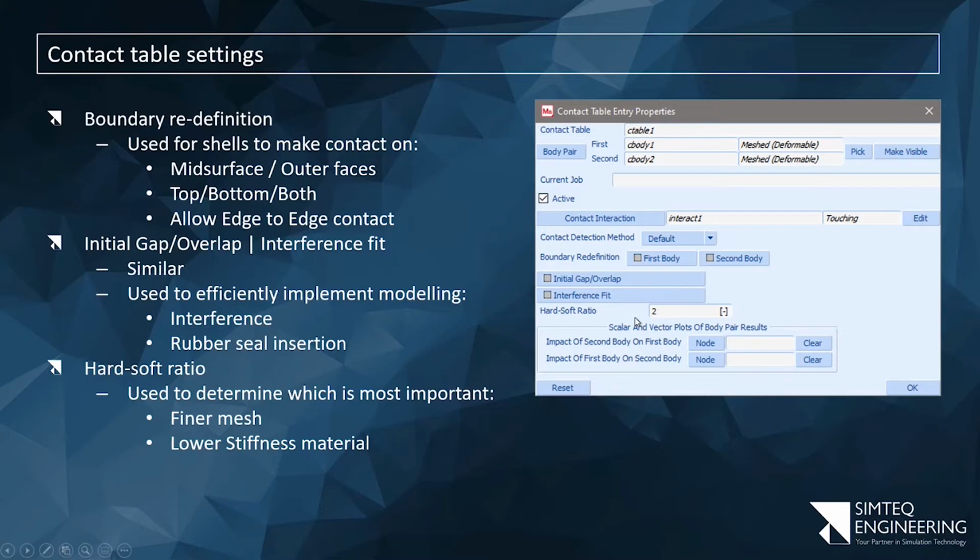It just opens that little bit of a gap. So what's the advantage of that? It's a lot easier to get really good answers for interference with using this method when I compare it to the mesh overlap method. On simple shell models and planar models, it's still possible to do the overlap method. I think one of the Marc standard examples actually does that, but try to do that on a solid mesh with meshes that don't tie up and so on. It's nearly impossible to get right. But as I say, doing it like this is actually really easy to do.